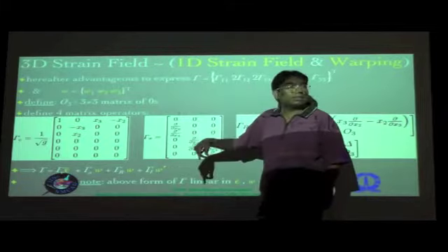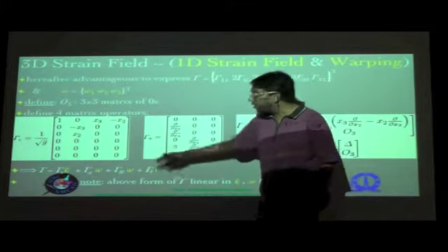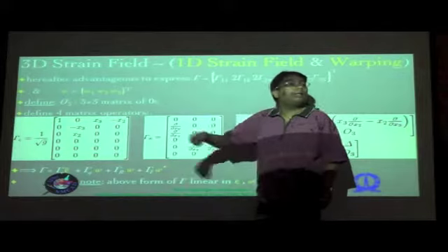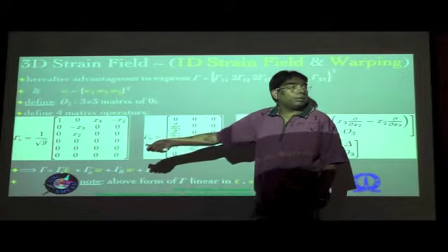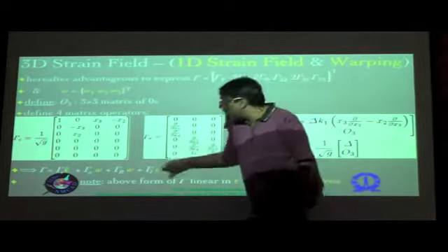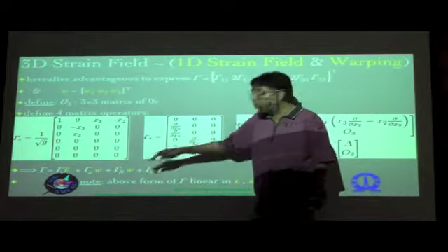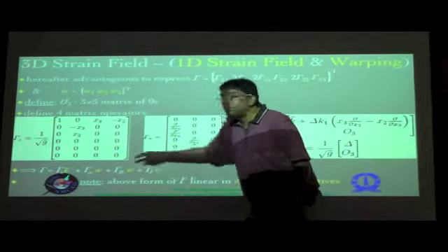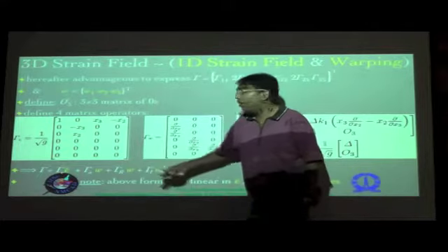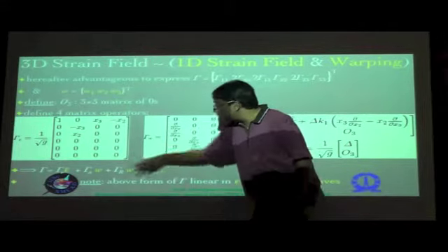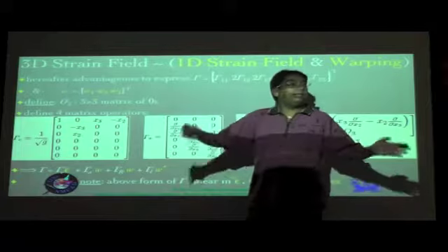But when we go to class T and class S beams, the solutions for W can have nonlinear terms in the epsilon bar components, and therefore you would see that in such a situation it is also possible that these terms can contribute nonlinear terms as well. But again, this is something that we are restricting to only the leading order terms.